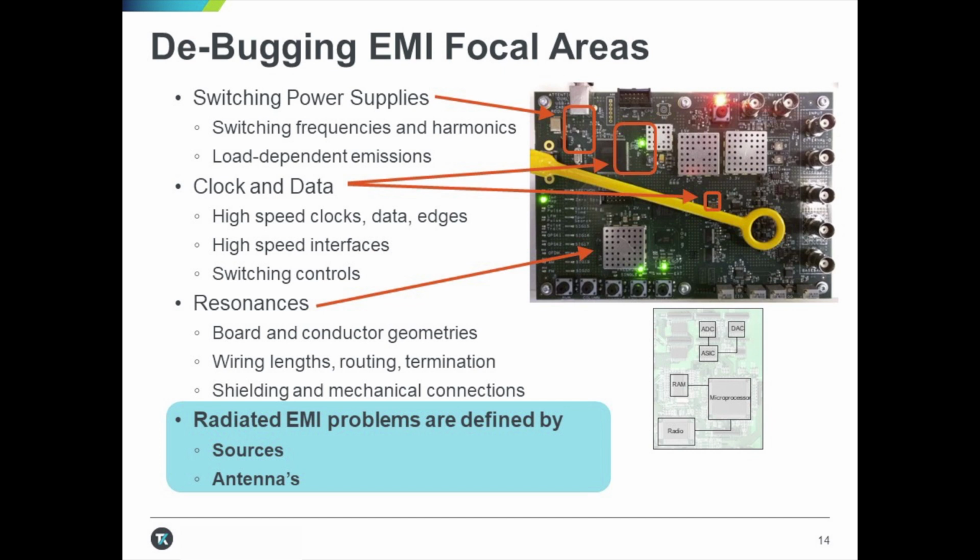In general, when I first look at a product, I will go to the power supply. The second place I'll go to is what I call the ins and outs of the product, or the I/O ports, which signals are coming into the device and which signals are coming out of the device. Do we have USB? Do we have Ethernet? Do we have RS-232? These are all the sort of things you want to look for.